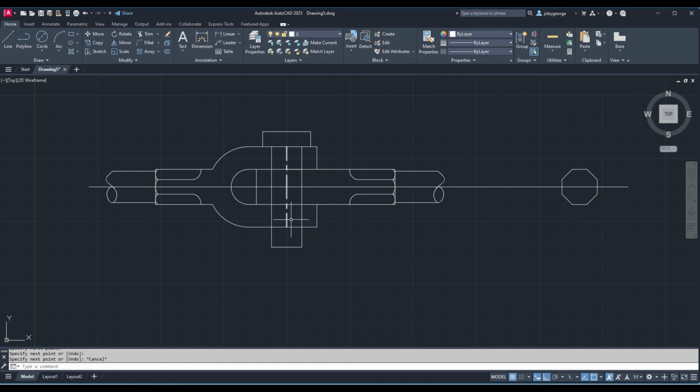This center line I can pull it downwards. Similarly, I will pull it upwards. I'll make it the center line. Now for shading, I need to draw splines and two sides to make that area closed. So I'll click on that, and make sure the ortho should be off. So I'm turning off the ortho.